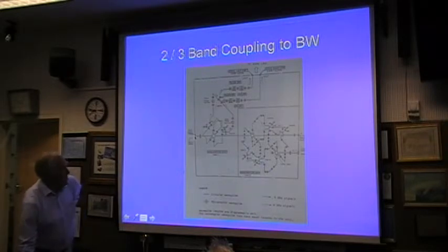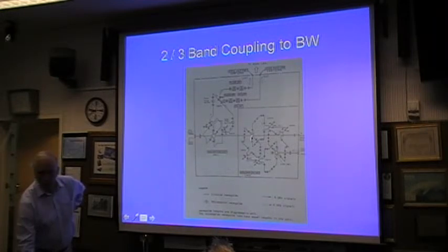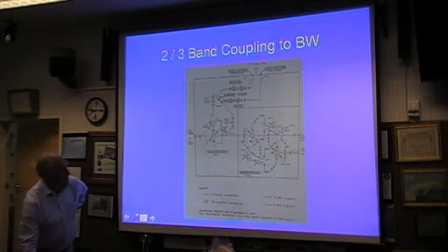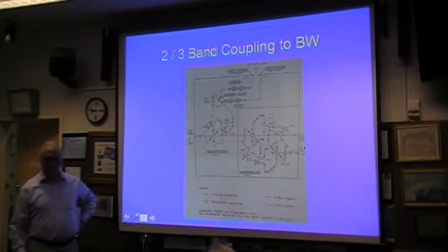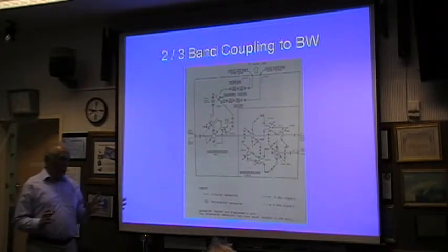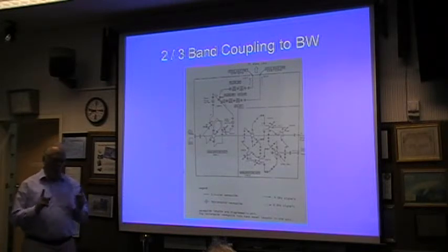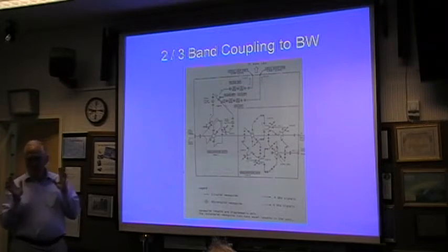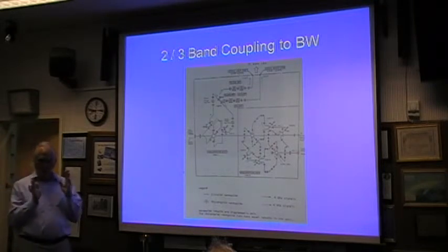So here's one band. There are 4 ports for each band. You've got left hand and right hand coming in. There are phase shifters and filters and things to launch or to receive the signals left hand and right hand. And a bit further down the horn is the same again for the higher band. Again, phase shifters and so on. And a bit further down still there's actually a Ku band feed on this. But because of the way it works, the illumination angle of a horn with a fixed aperture is inversely proportional to the frequency, or inversely proportional to the wavelength.